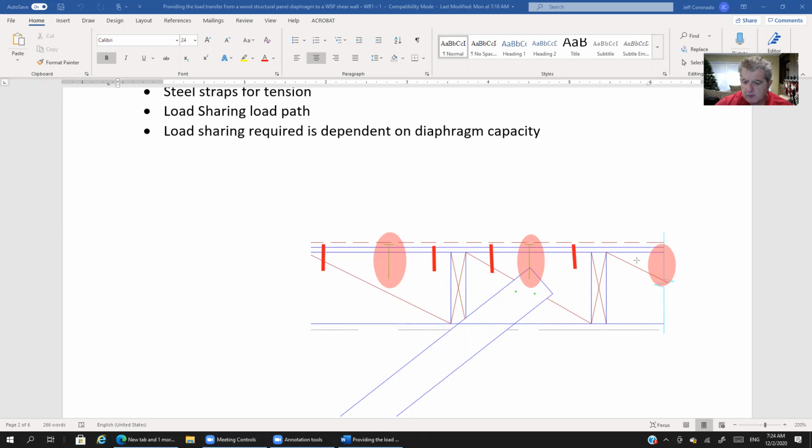we're going to have nails that connect the wood structural panel component of the diaphragm to the blocks. And typically, those are what we refer to as diaphragm boundary nailing. And typically what you might see is maybe 10Ds at, let's say, 6 on center, all right?